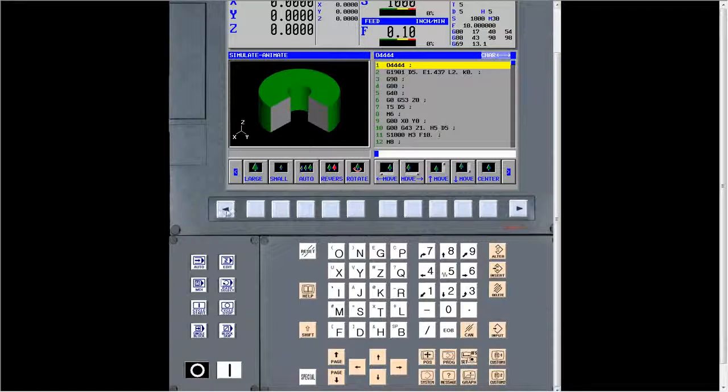So see now the cutouts where we can see it. And that's what's good about the rotation. You can get the blank to look however you want it to look. When we press start, we see the tool go all the way through and make one rotation and then come back out. So that's type 1 thread milling.